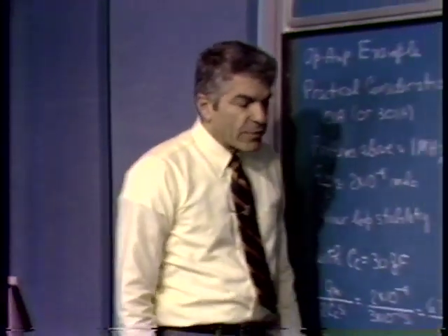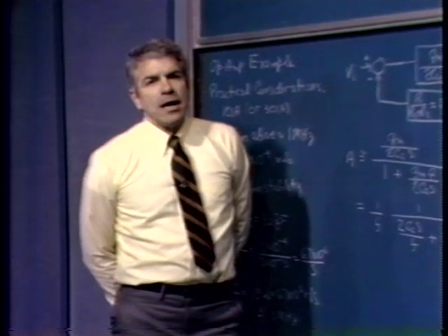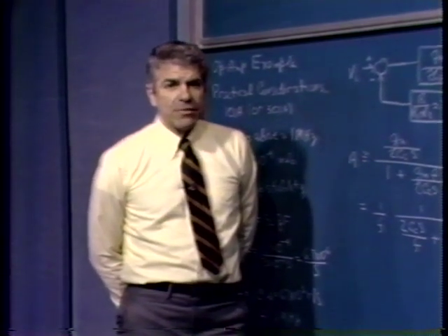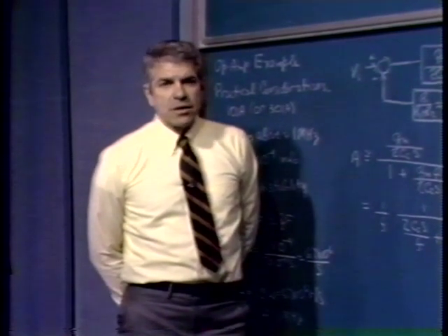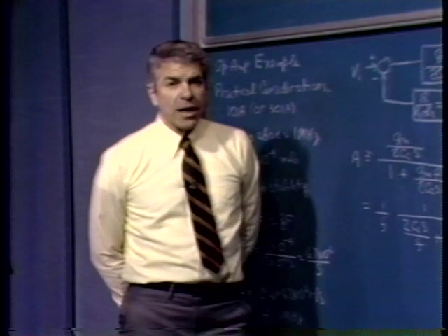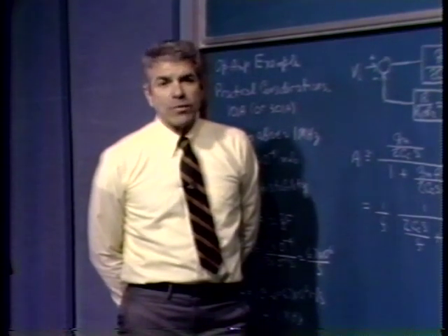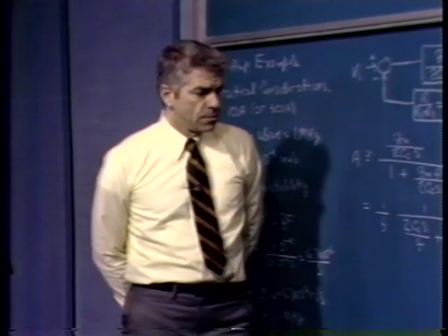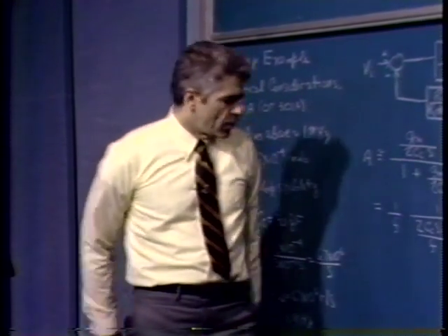Well, single pole compensation is a very good general purpose kind of compensation. It's the one that's normally used when fixed compensation amplifiers are sold. It can certainly be designed so that the amplifier is stable in a variety of feedback connections. It's only, or one of its problems, is simply that it's overly conservative in many applications, as we've seen. Another possibility is to consider the following.